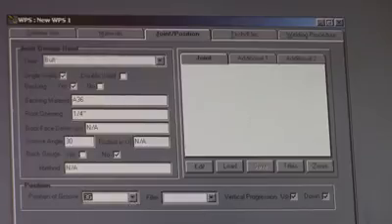It's in a 3G position. That way it'll qualify you, and we're going to do this according to, again, the AWS D1.1 structural steel welding code. That's kind of what we use. The position is 3G, so it's going to pre-qualify you for numerous positions. It'll qualify you for 1G, 2G, and also 1F, 2F, and 3F in the fillet weld world. But we don't have to do that.